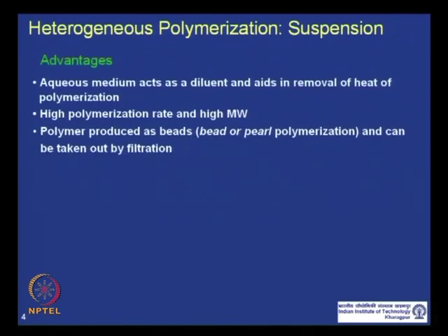The advantage is that you have this aqueous medium present as a diluent. So, the heat generated by the polymerization reaction you can easily take out because of the dispersing medium. So, there is no such problem as in the case of bulk polymerization, and because the concentration of monomer in those monomer droplets is high, similar to bulk polymerization, the rate of polymerization as well as the molecular weights are also high, and the polymers produced in this case are in the form of beads, droplets.